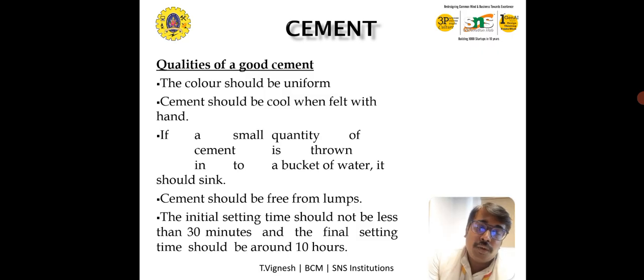So this is the most important thing. The initial setting time should not be less than 30 minutes, and the final setting time should be around 10 hours. It is the duty of a civil engineer to make sure this is achieved in construction. I think this is all about cement.